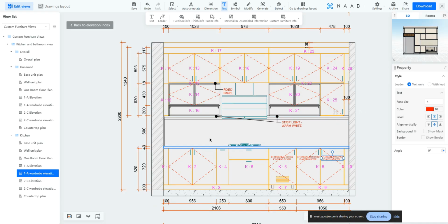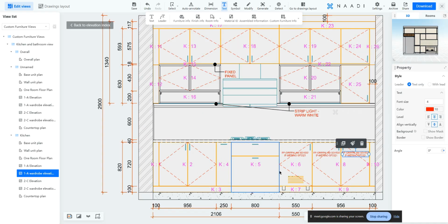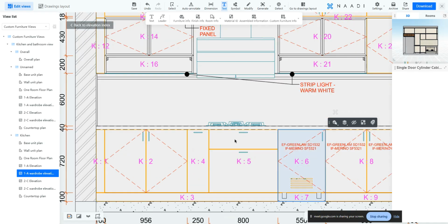And apart from that, another common requirement which designers come across in their elevation, especially the external elevation here, is your hatching, right? So you have that common requirement to add a hatch, especially to denote the finish differences. So yes, here you can add a hatch. If you are able to select a surface, you are able to add a hatch. For that, you just have to first select the surface.